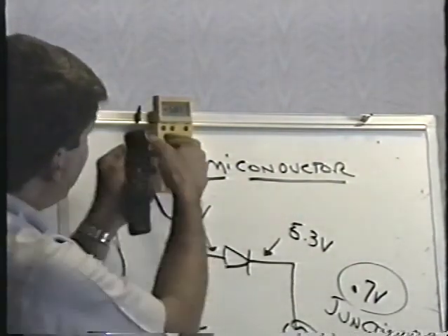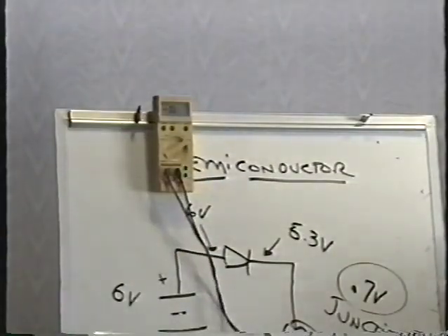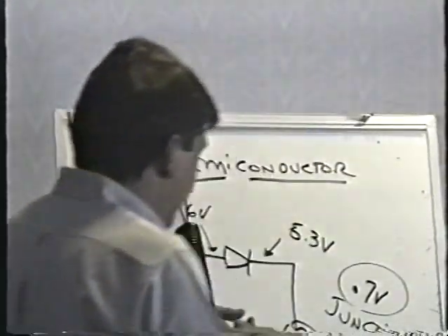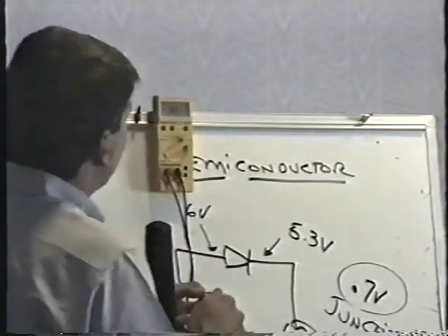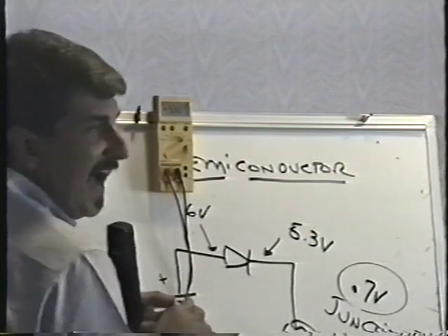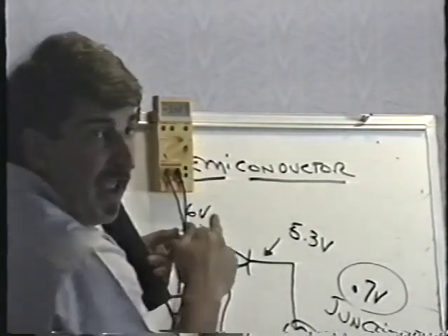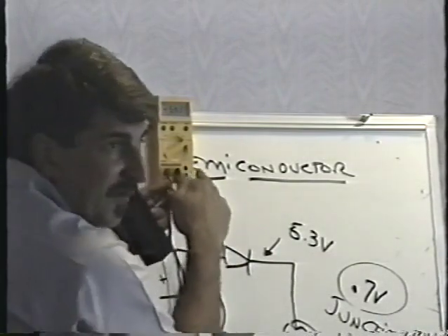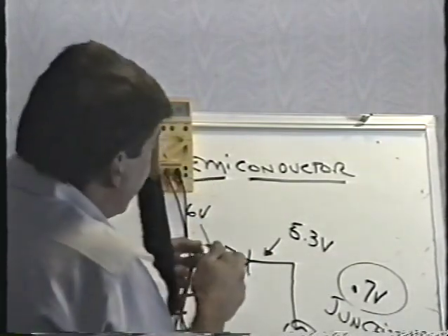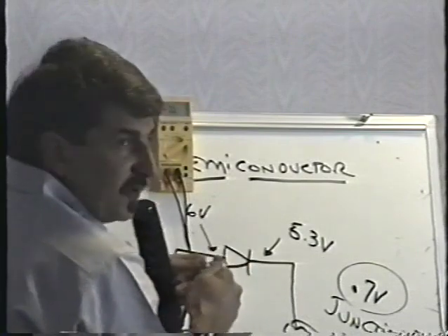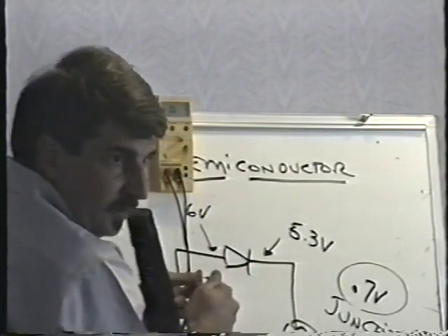Now, here's the little teeny diode. It says 0.584. If I go to the larger diode, it should show me something somewhat lower. It says 0.53. The larger it is, the lower that will be. Even if this read 0.49 or 0.48 or even 0.45, as long as it reads open when I reverse the leads, it is good. Right?